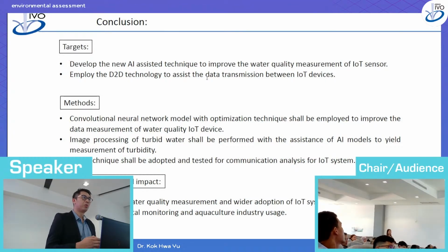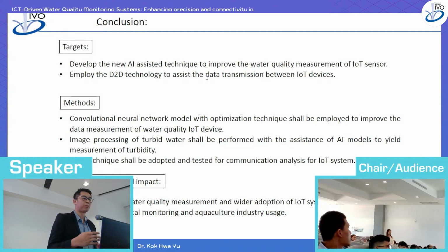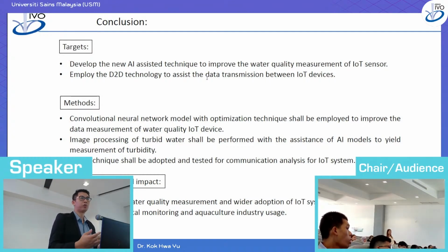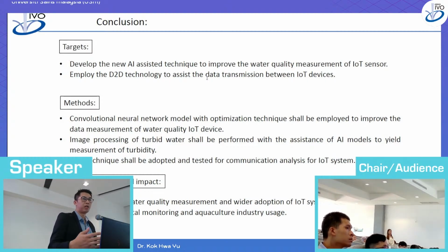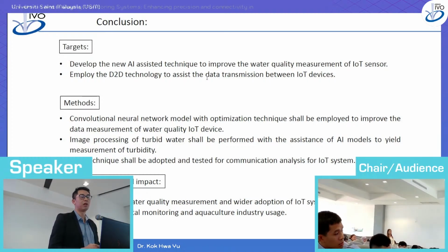To make sure that the prediction by the IoT sensor is within a satisfactory range, we have to do some calibration. Sometimes it's offset calibration, and sometimes it's white noise calibration. There are certain procedures that we need to do, but comparison with a commercial unit is the important process.